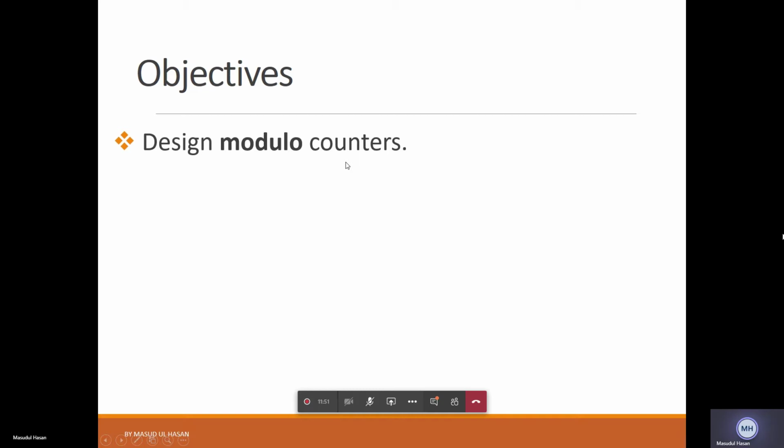So we are going to write a code for the counter which will not count up to 9 only. It will be exactly the same code, but at the end, instead of comparing it to 9 or 99 or 999 or 4 nines, it will count up to 8 nines. So this will give us exactly 1 hertz frequency.